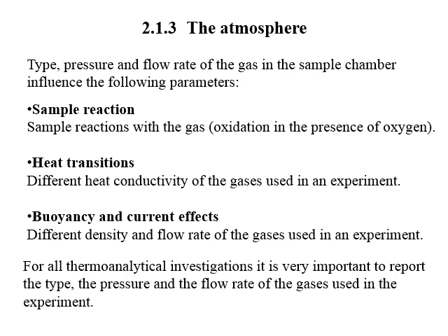It's also important to understand, though, that changing the gas actually changes the heat conductivity in the TGA. So something like argon, which can conduct heat better than something like air, will change the rate at which the heat is transferred to the sample. Additionally, changing gases will affect buoyancy and convection effects. Because as you heat the gas, the density of the gas changes, which causes a buoyancy impact on the sample. So the sample will appear to change weight as the buoyancy changes inside.